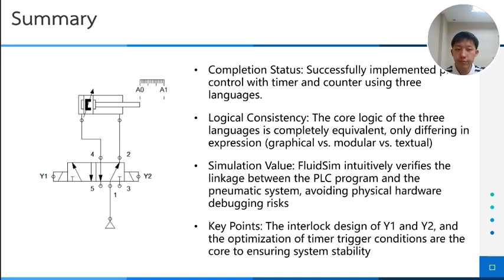Fourth, key points in the whole control logic design. The interlock design of solenoid valves Y1 and Y2, and the automation of the timer trigger condition are the core, to ensure the stable operation of the system and avoid action conflicts.